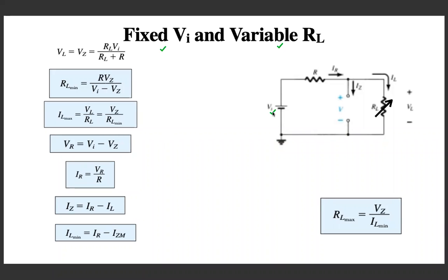So the very first thing is the same step one we discussed in the last lecture also. Just open circuit the Zener diode and try to calculate the value of this V. This V is equal to VRL in this case also. Right now we are taking RL as a simple variable. So the voltage drop across the load resistance will be equal to IL times RL, and the value of IL we calculated in the previous slide.